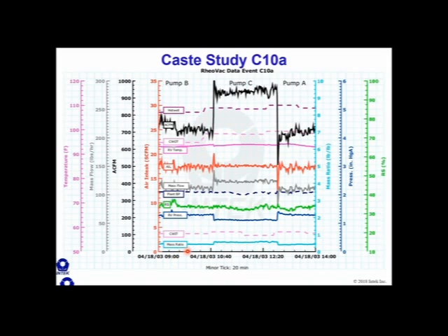Right. Okay, and so is the vacuum pump capacity up where it should be? I've stated that most pumps should be operating about 1,200 to 1,500 ACFM, especially these Nashes. No, they're not. That's right. So we got an answer. So are all 3 of these pumps not working right? Yeah, they're all not working up to specification. That's essentially what this is boiling down to.